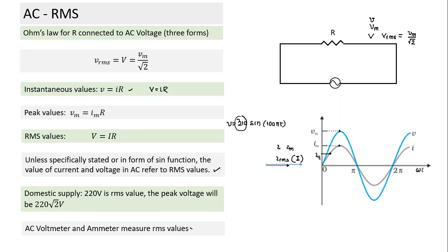So these are very simple points. Galvanometer, sir? Pardon me? It doesn't use a galvanometer. It works on heat generated. It doesn't work on the galvanometer principle. You understand why a galvanometer can't work here? Yes, sir. It'll keep fluctuating, and too often. It completes 50 cycles in a second, so it will be too rapid, and we can't see anything happening. It will not settle down to any value. So we use another principle, which we don't discuss, but it works based on heat generation.